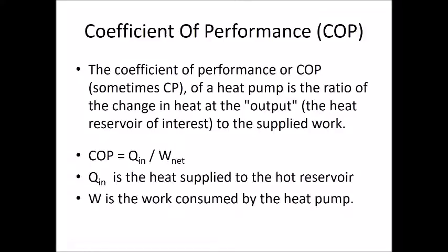Now, as we go through these slides to the end of the lecture, I'm going to get you to write one or two things down and then compare them. So if you don't have a pen and a paper handy, just pause the video, go off and get a pen and a paper, and write these things down as I say, okay, write that one down. So the first thing I want you to write down is this: for a refrigeration process. So write refrigeration and then write COP equals Q in over W net. Okay. So once you've got that, we're going to move on, because what we'll do is we'll actually compare that to our heat pump later on. Okay.